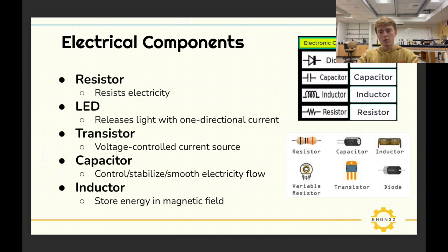If we're talking about a bipolar transistor, BJT, then it's a current controlled current source. In that case it becomes the base, and then the collector and emitter regions. I get to control the current flowing through the collector and emitter regions based on the current flowing through the base, okay?